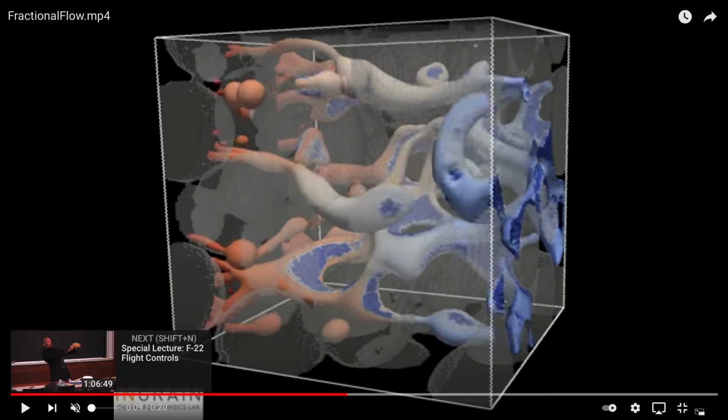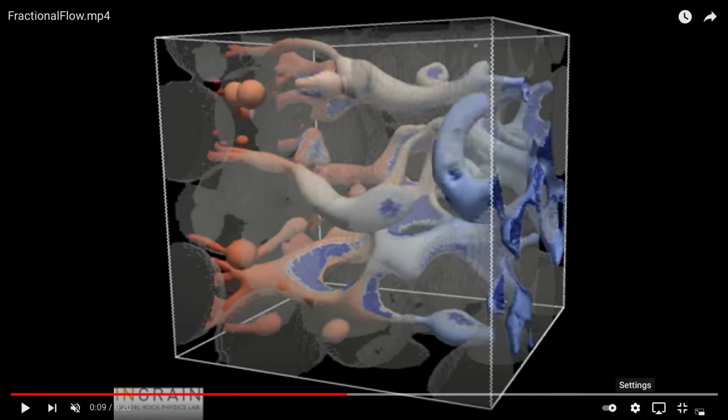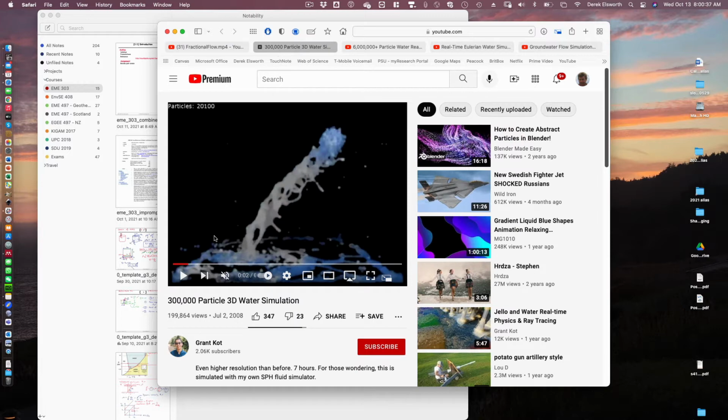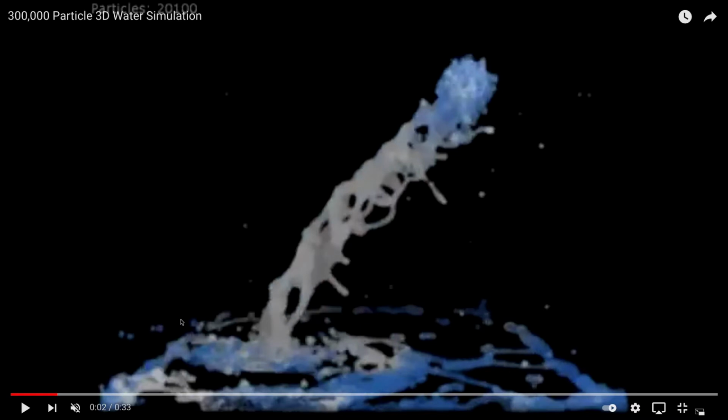This company was bought out by Halliburton, I think, so it's no longer a separate company, but that's what they do. An interesting idea. That's in a porous medium, and we'll find out if we get to it today that in a porous medium we can throw away the v squared over 2g term. Inertial effects of flow in porous media don't matter because the velocities are so small compared to the viscous losses of the fluid. That's one way of looking at it.